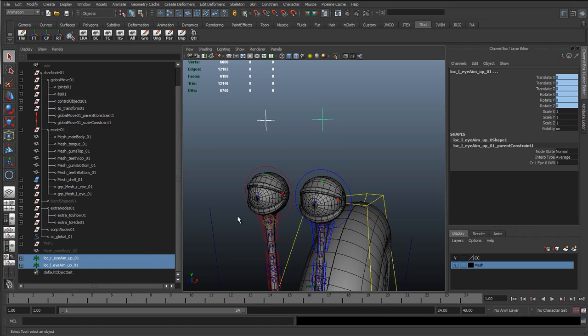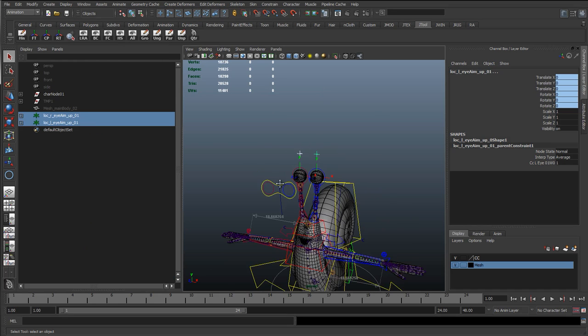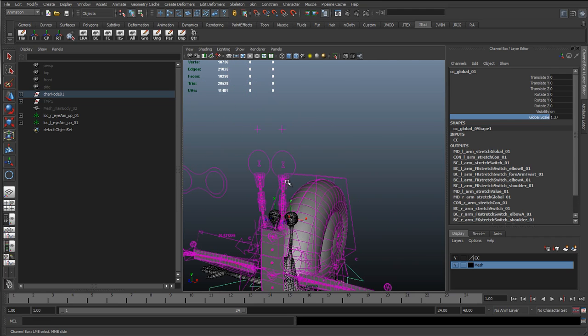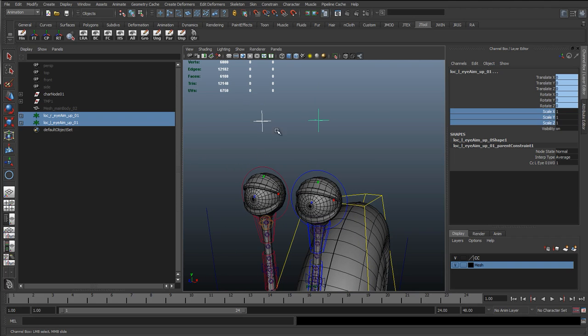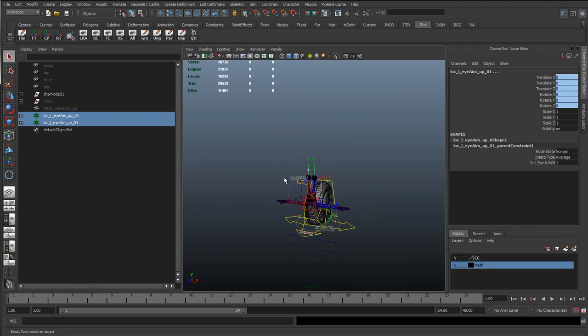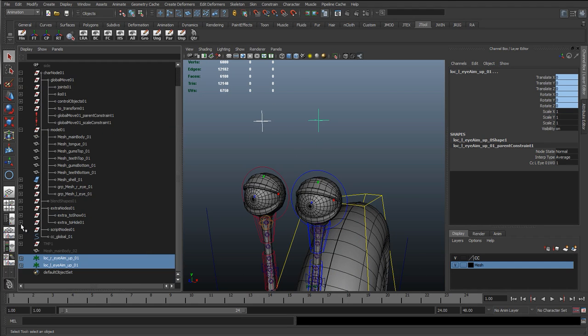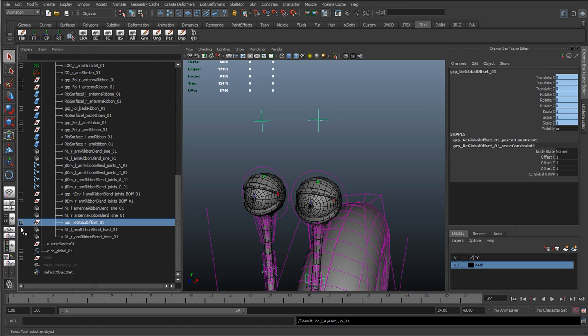And these two, because they're quite similar to the tie controls, I'm just going to put them in the same tie controls group, because we want them to scale with the rig. Because if you think, if we scale this rig up, so I'll just do it now actually, if I scale these up, well, they're going to follow along, but I just want to get them in that same group as well, because there's nothing directly tied to the scale. And they're following up because they're matching the position, but they're not scaling as well. So just to keep it consistent and keep it connected up, I'm going to put them in the group tie offset group.